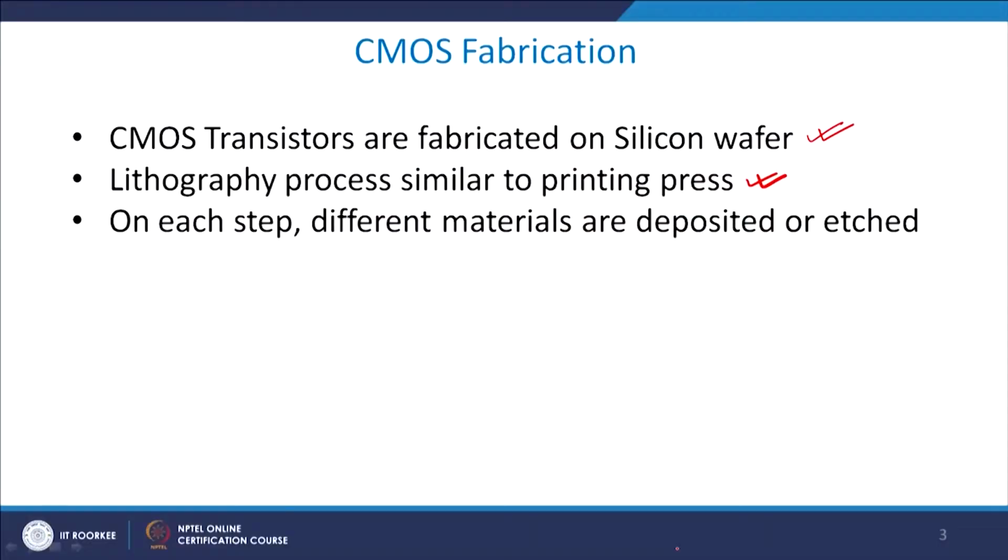If I want to grow, for example, just the contact, maybe I will be using something else, maybe I will be using aluminum to do that, and so on and so forth. So, depending upon the usage of those lithographic techniques, you generally have photolithography and electron e-beam lithography, or direct e-beam writing also is there, but these two are the most important ones. Photolithography, as the name suggests, is very simple.